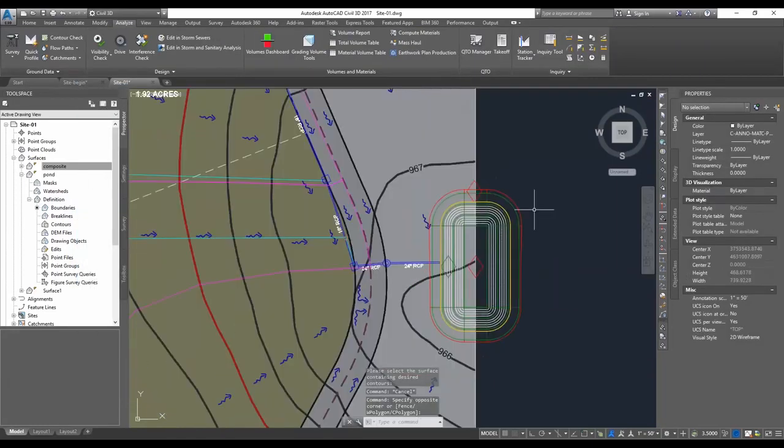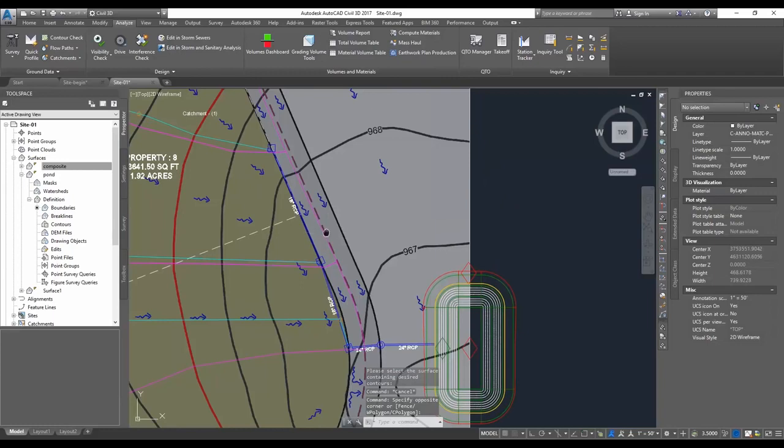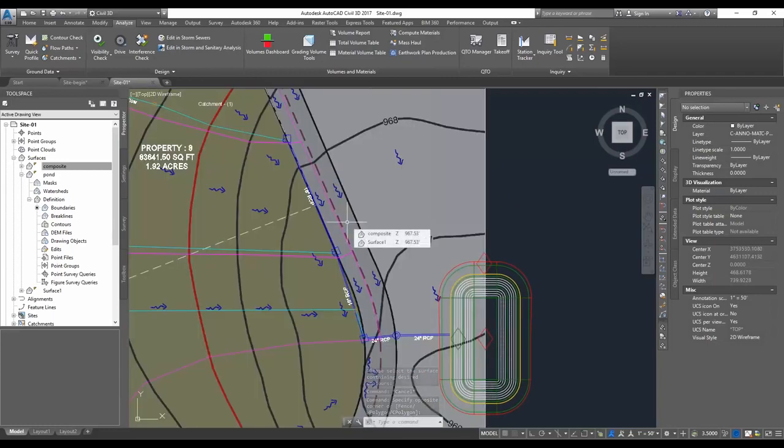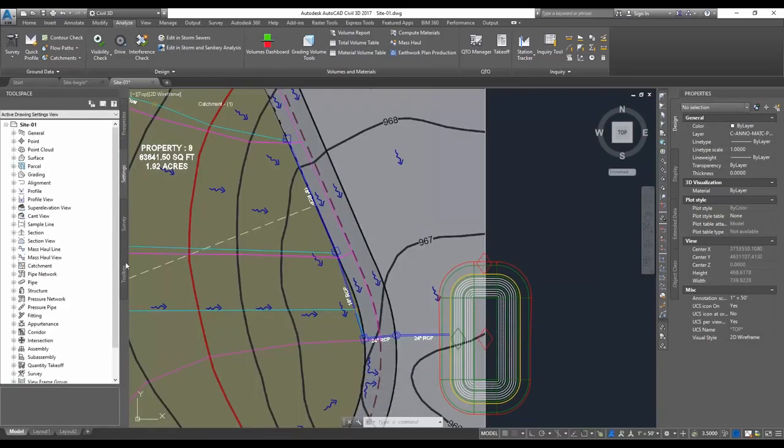So that's all out. Now let's export out to SSA. Before we do that, we'll go into settings, and I'm just going to show how things are translated. You may be familiar with the older software used in conjunction with Civil 3D, Hydroflow Storm Sewers. It's actually going to use the same file type to push things out, and some of the same part matching takes place.